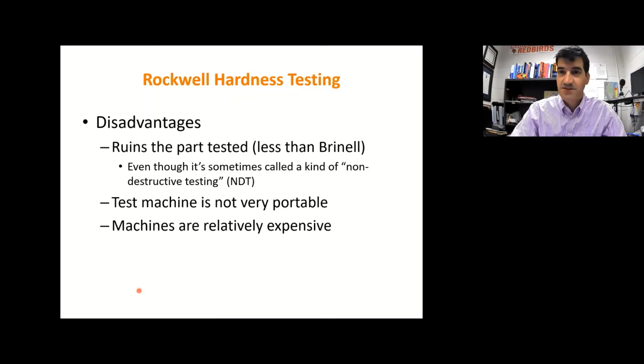The disadvantages of the Rockwell test: well, it kind of ruins the part. I mean, it doesn't break it, and it's sometimes called non-destructive testing, NDT, but you can't take this part and sell it afterwards, because it's going to leave these indentations. You'll see in lab 3, it's going to leave these little indentations in the specimen. So you can't really turn around and use that part or sell it to a customer. So it may not be destructive, but you can't use the part again.